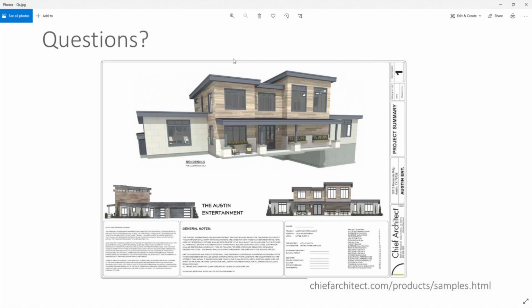So this garage gable, which is the 10/12, now when I do the auto return, the pitch is 10/12, but it's in the same direction and plane that my 4/12 pitch is. Is there any way to change that auto return to be a 4/12 pitch instead of the 10/12, or do I have to do a manual roof there and create my own?